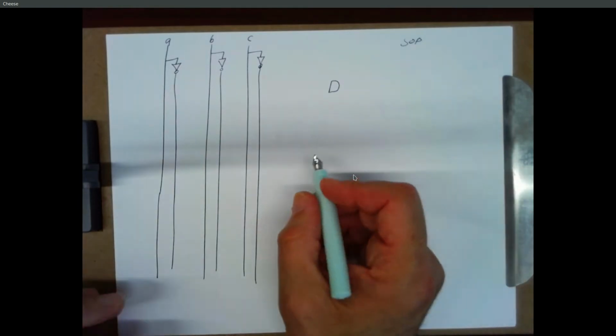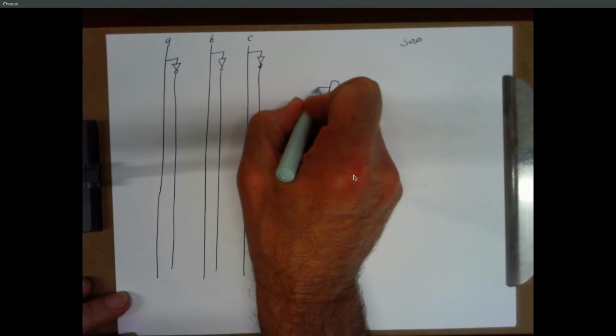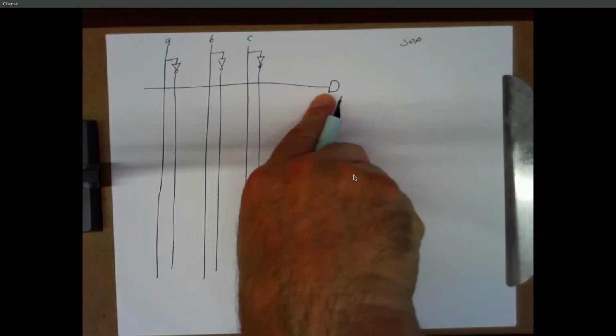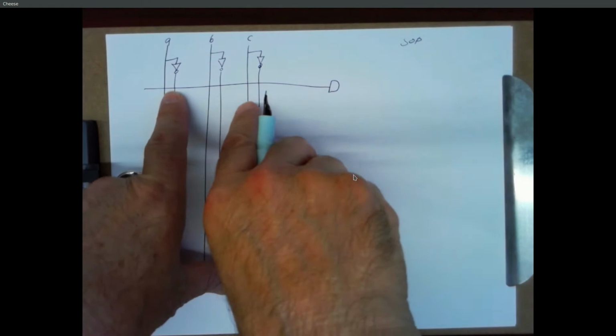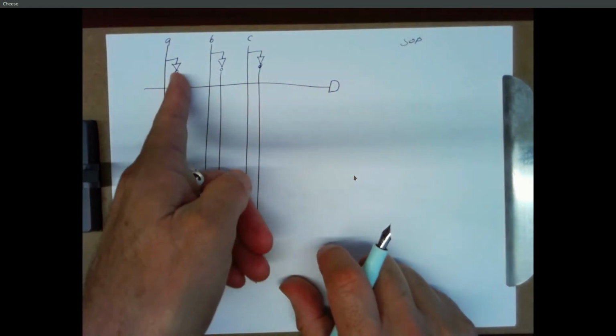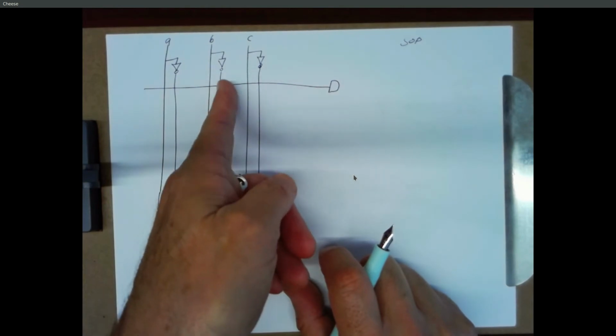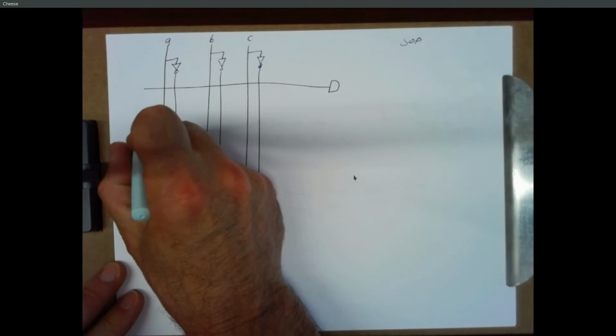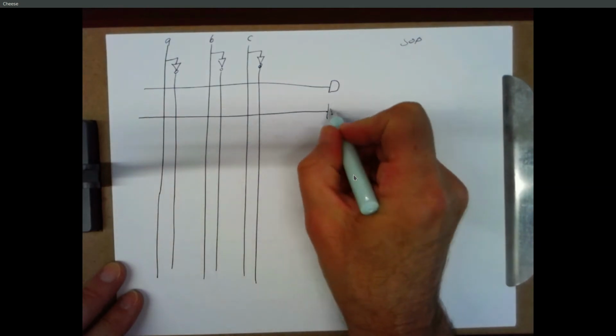And if we're using an FPGA and we're drawing a fuse map, the way that the connection should be drawn, we use a shortcut, which is we just draw a single wire, and we're going to draw an X where we want a connection. And we have to understand that there's multiple wires going into this AND gate, and if we have an X here and an X here, it means we have one wire coming from this line A bar and one wire coming from this line B bar going into our AND gate. Okay, so it's a shorthand, so we can have a series of these.